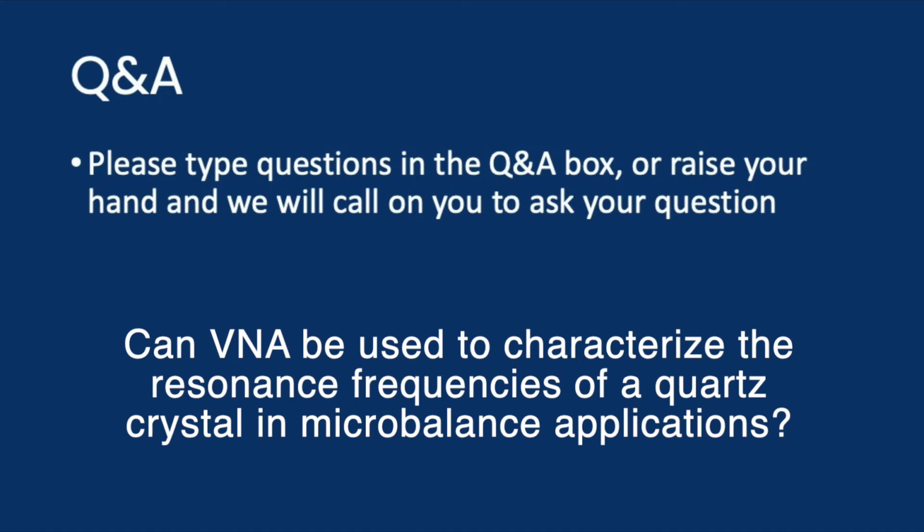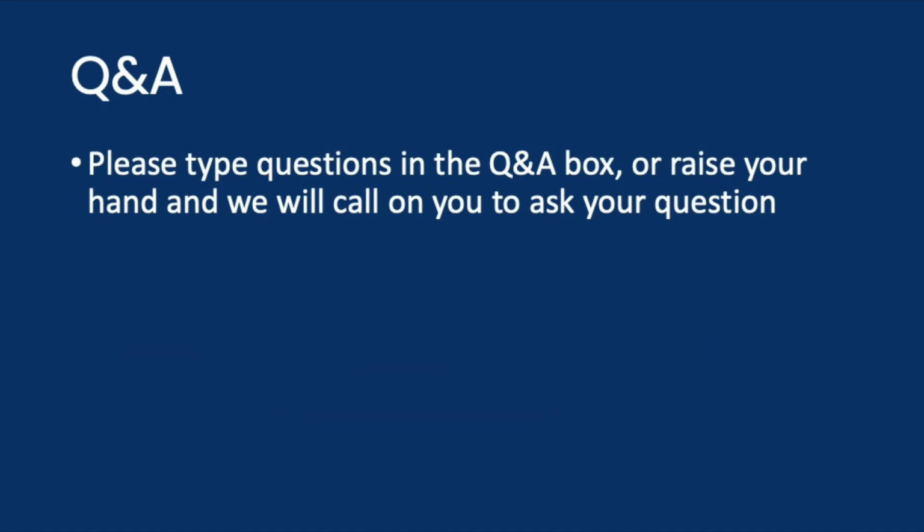And we do have an option, I think even starting in the mid range, where we can get frequency points down in subhertz steps. So if you do have a very narrow resonance, you can very accurately characterize it from a frequency and amplitude perspective.